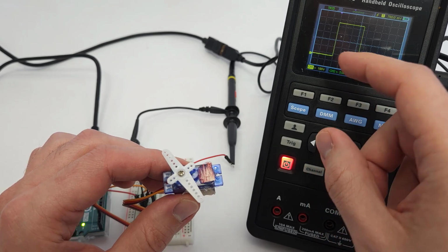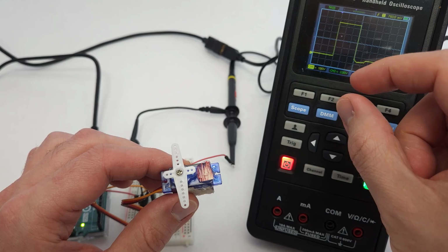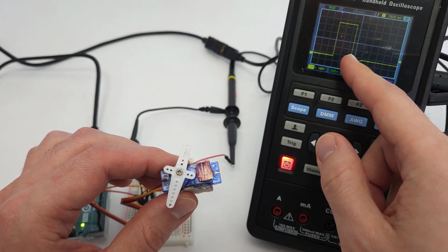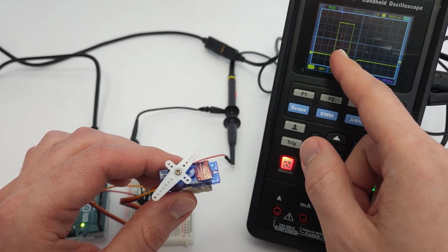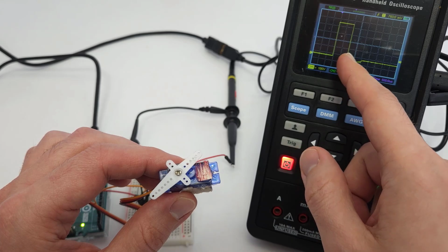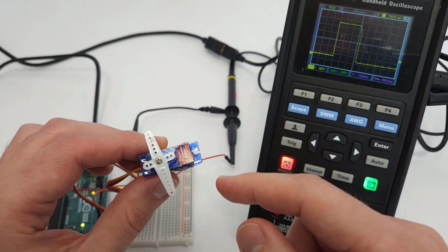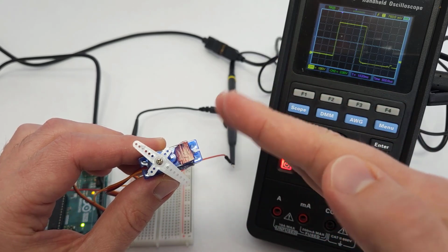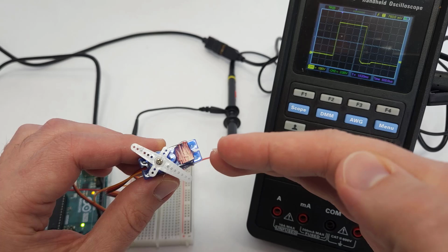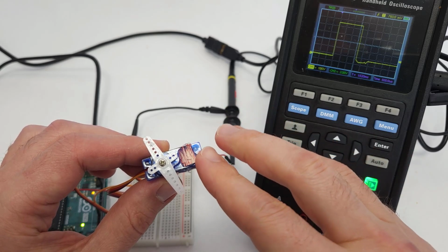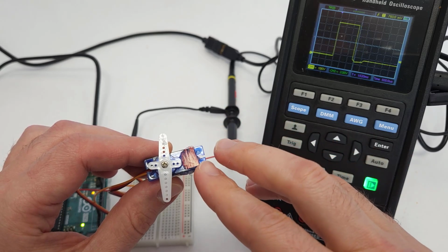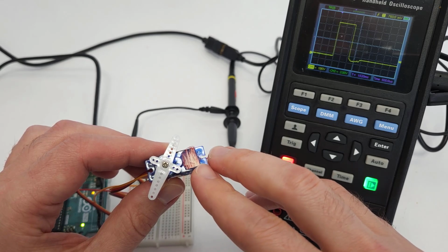And again, since I'm only using an 8-bit timer and I have such a low resolution, we can see these pretty discrete jumps in the duty cycle as this pulse jumps from one position to the next with a 1-second delay in between. And we can see the corresponding discrete changes in the angular position of the servo, where since I am only using an 8-bit timer, I cannot really do better than that.